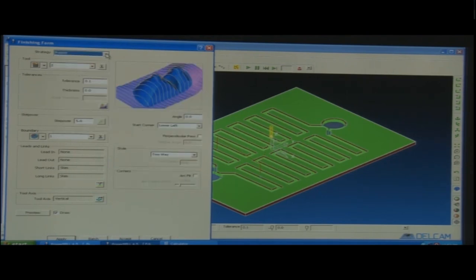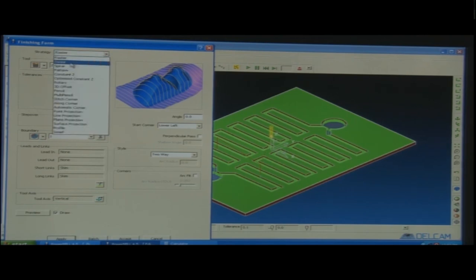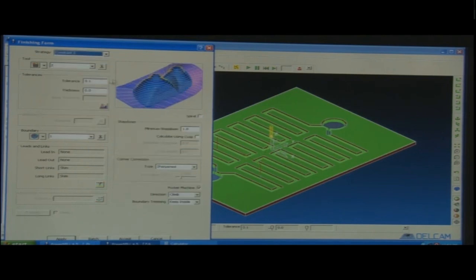So, there are certain ways, again radial, raster. So, depending on the part, where the part has to be matched with another part, putting the right tolerances, we have to machine it accordingly, selecting this finishing form. This is all again the skill of the operator or the user who is selecting the different strategies here to machine to make the proper match, whether the fit is a push fit, whether the fit is a loose fit or tight fit, all that also depends when the surfaces are matching.